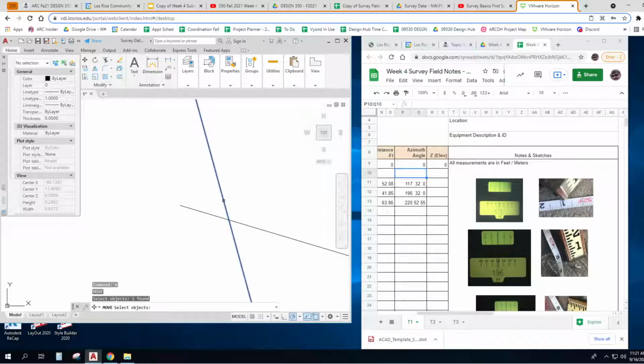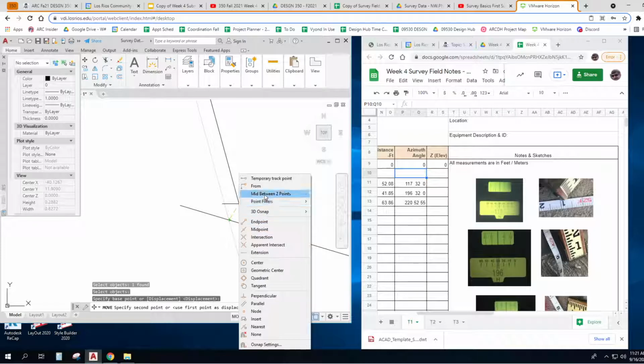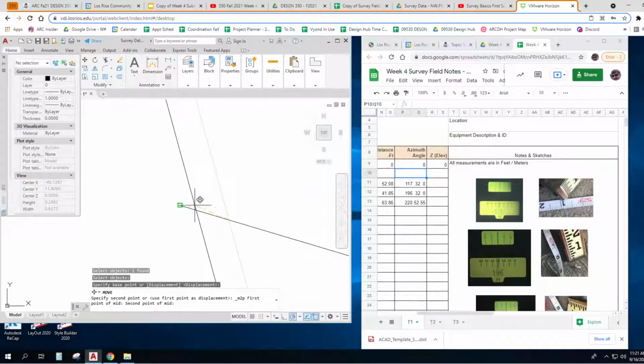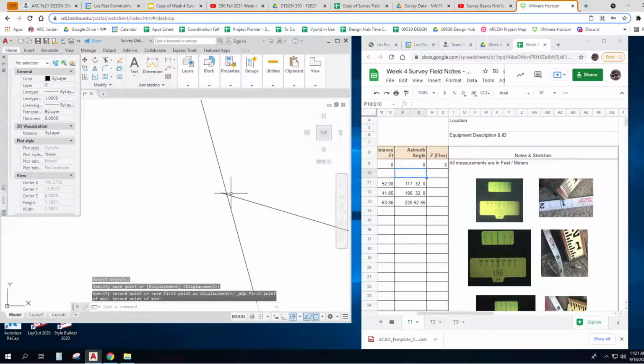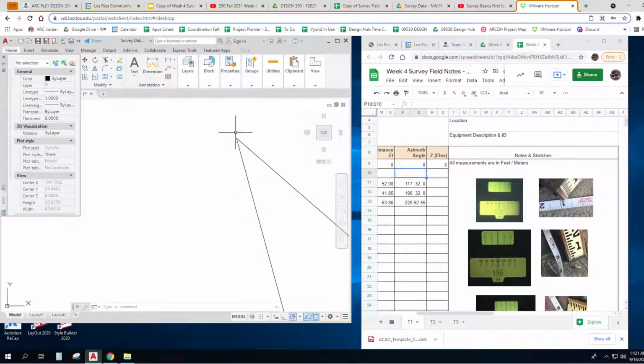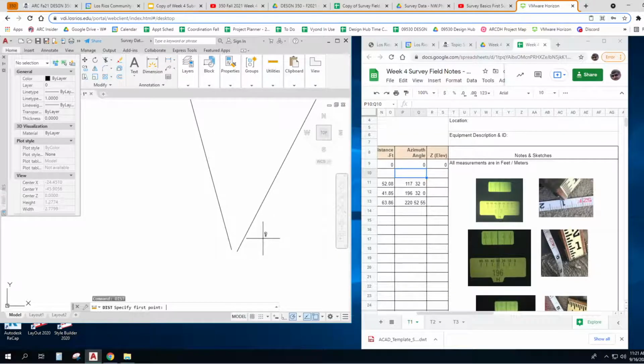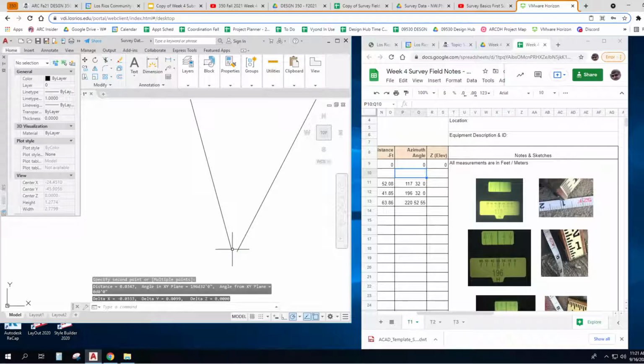Move this object from this point midway between 2 points, here and here. So now that's off a little bit. This is off a little bit. And this is off a little bit. This is called rectifying. If I do the dist command, 0.0347.